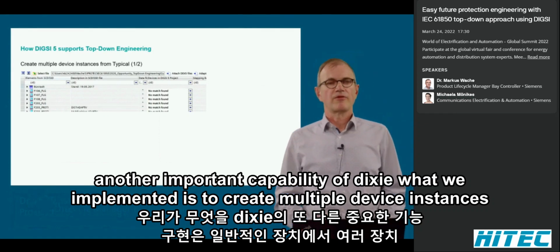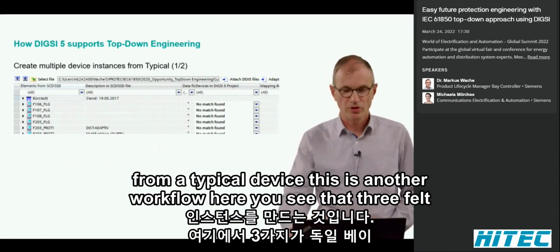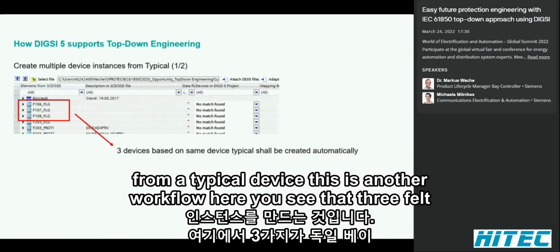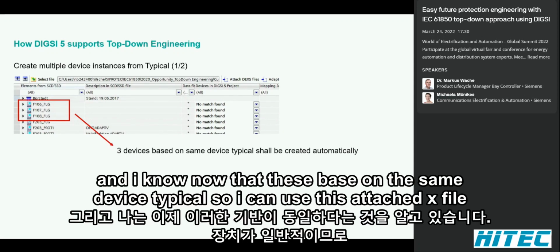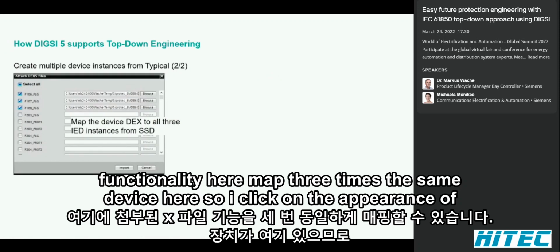Another important capability of DIGSI, what we implemented, is to create multiple device instances from a typical device. This is another workflow. Here you see that 3 Feldleitgeräte, in German, bay control devices, are requested on the left side of the editor. And I know now that these are based on the same device typical. So I can use this attach text file functionality here, map the same device 3 times here.